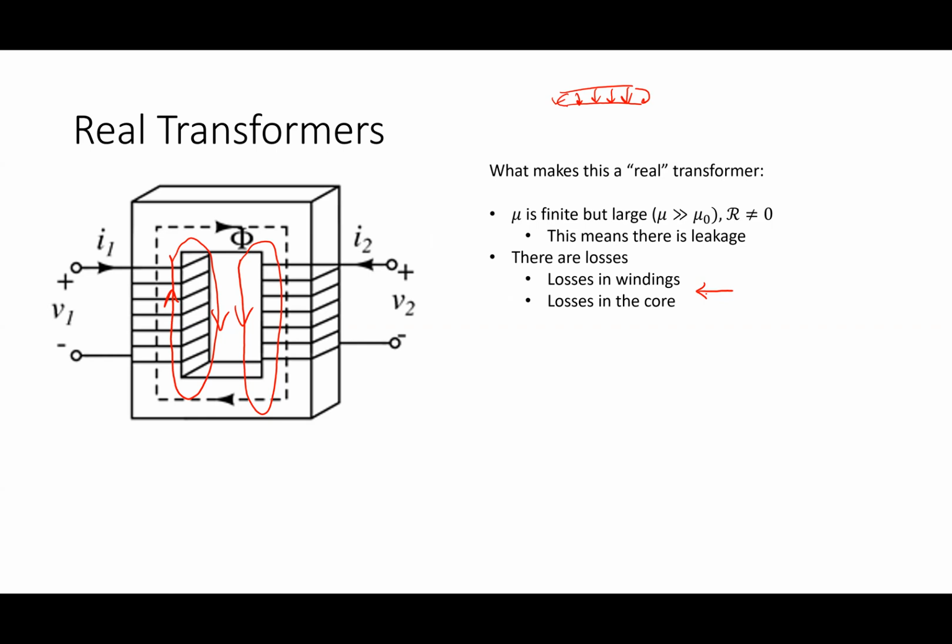Conductivity. There's magnetic fields going through this iron material, and that's going to create currents inside there, because changing magnetic fields create currents. We don't usually worry about the details of that other than to say that there's losses. When I said there's losses, what that means is some power going to that primary is getting bled off somewhere. And if I touch a transformer, it's hot as a result of it.